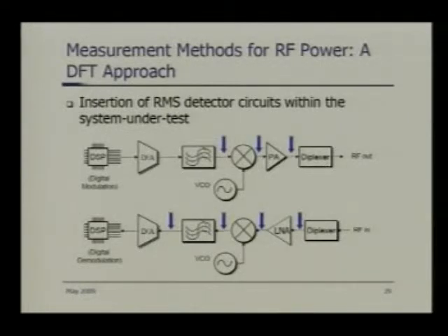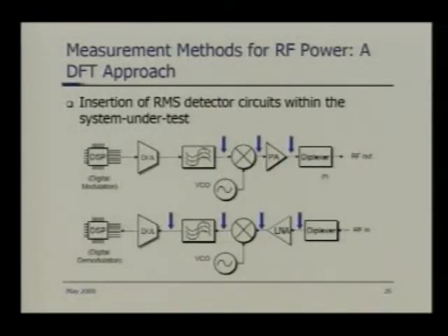The idea of the diplexer is that in case of transmitter and receiver, let's say your cell phone, your transmitter and receiver are working simultaneously when you are talking, right? So if the cell phone front end is working at, say, 1.9 gigahertz, both the transmitter and receiver at exactly the same frequency, then since the power level of the RF output circuitry from the transmitter side is so high,